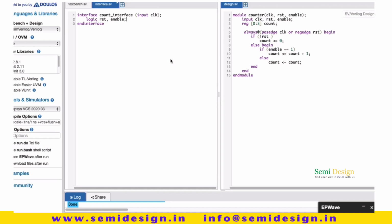Similarly, we can use it in different modules. If we study the test environment, we have different modules, like driver, monitor, and scoreboard, which will use the signals. So the major advantage is that the interface is declared only once, and the handle is passed across many modules and components. Addition or deletion of signals is easy because we only declare them once, so it is a lot easier to add or delete a signal. So this is all about the interface concept.